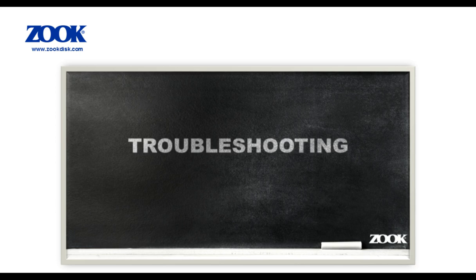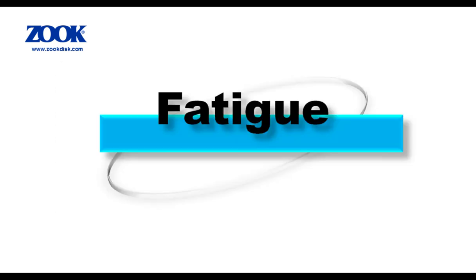It's important to remember that a rupture disk is a device that's designed to burst. Some people say it's designed to fail, but we like to say designed to burst or activate at an exact point. But like any engineered mechanical device, things can happen to affect performance, and this is when disk manufacturers have to use some detective work. First and foremost, rupture disks will not last forever. They're tensile devices exposed to various forces, temperatures, etc., and therefore they will fatigue. Sometimes bursting low or early is simply a case of service life.